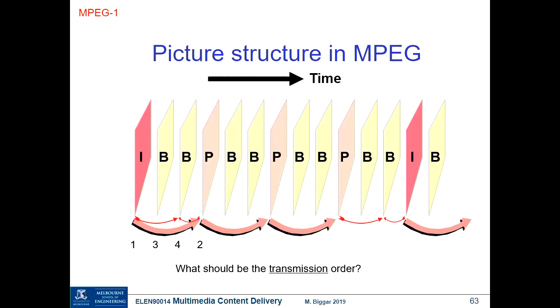Buffering can be avoided. If you can send them in a time sequence, buffering can be avoided at the decoder. Otherwise, there would be more buffering required of the decoder. Which one is going to be decoded first before the second B? Well, you would decode this one and display it because it would be the earliest one to display. Once it's displayed, you can throw the data away and free up the memory to deal with the next one.